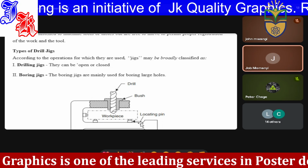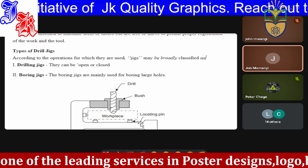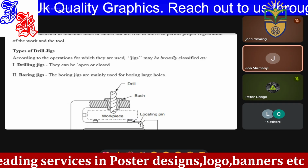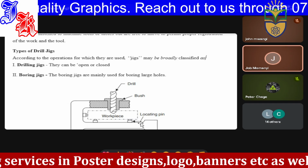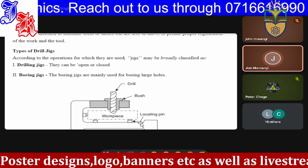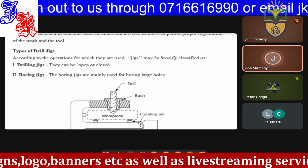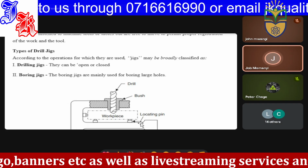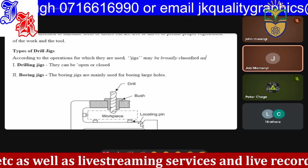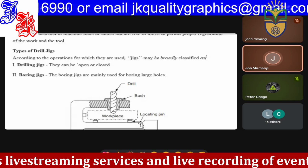So in our normal workshop, we normally clamp our workpiece using, for example, a vise. You locate a workpiece accurately using a vise. That is after you have marked your workpiece where you want to drill your holes. Then you turn down the levers so that you can bring down the drill bit to that marked point so that you can start the drilling.